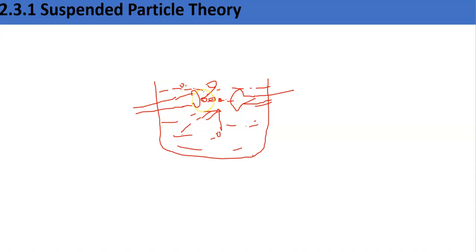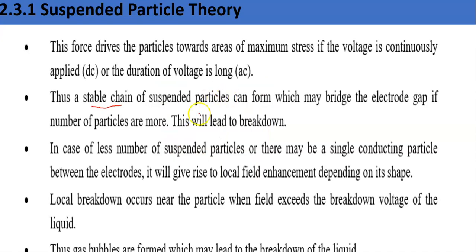So what will happen? The insulating strength of this will rupture immediately and it will start conducting. Ionization surrounding this will take place. Heat will generate, gas will generate, and then the temperature surrounding this particle will burn it out. Then all the weak gases and the burnt particle products will be formed. So this will lead to breakdown.